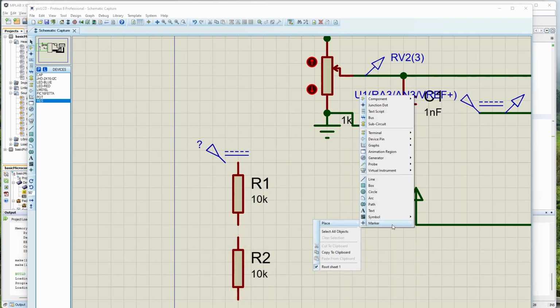We also use a capacitor as a filter, as I told you. Generally we will use it. This is hardware averaging, or you can do it in software, where it takes 25 samples and averages them out. Doing both is always better.